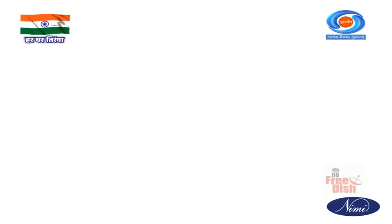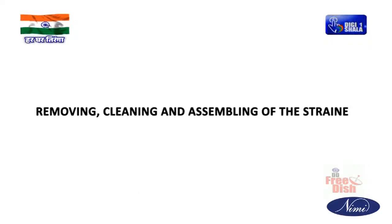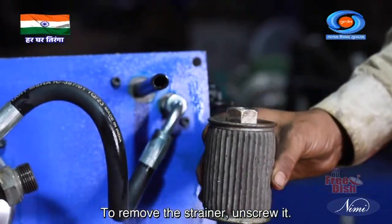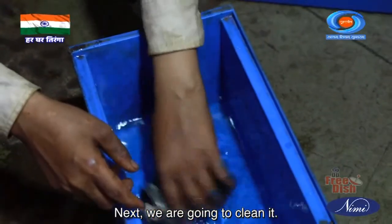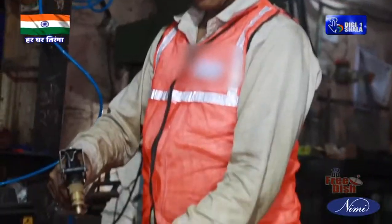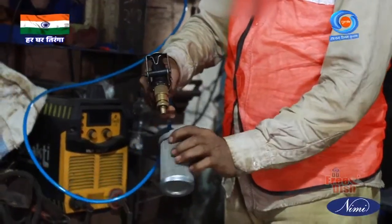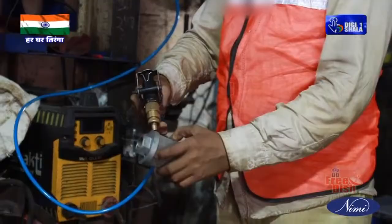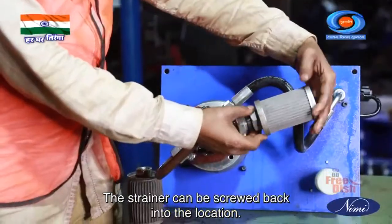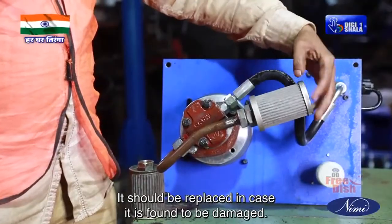Skill sequence. Let's next remove, clean and assemble the strainer. To remove the strainer, unscrew it. Next, we are going to clean it. To do so, soak it in thinner and blow compressed air on the mesh area. The strainer can be screwed back into the location. It should be replaced in case it is found to be damaged.